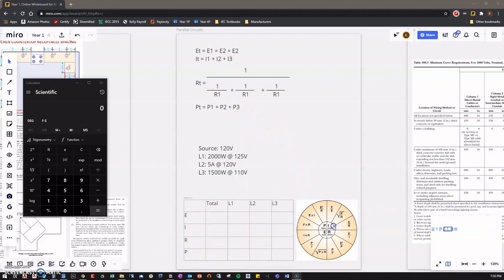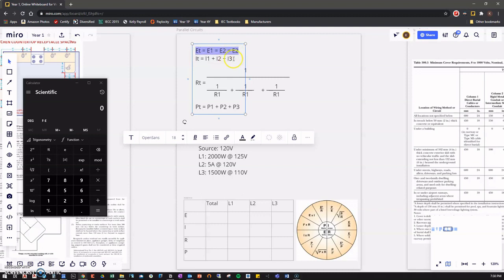So first of all, we have our Ohm's law. We're still going to use Ohm's law to help solve this, but we also need to recall our parallel circuit rules, right? Our voltage is going to be equal at all points in the parallel circuit. Amperage is going to be additive in that parallel circuit, so all the loads add up. Resistance is this big, terrible formula. I'm going to show you once again a way to avoid that formula because it's terrible, it's difficult, it's complicated. You're going to make a mistake. And then our wattage is just going to be additive here once again.